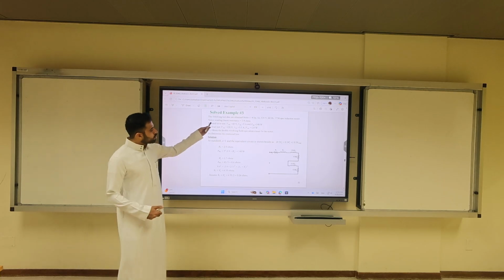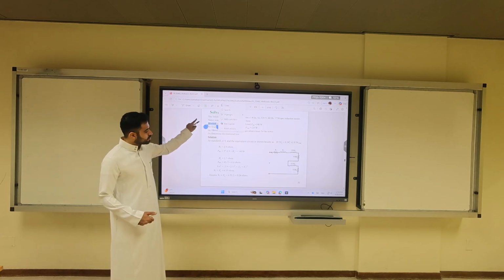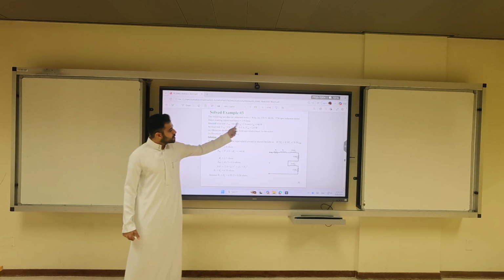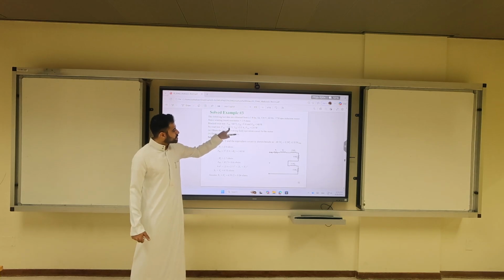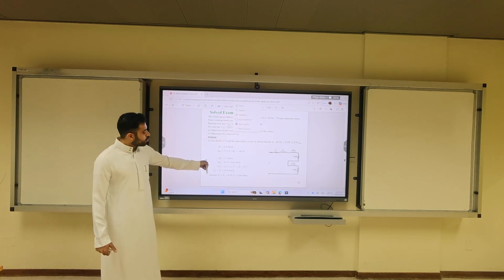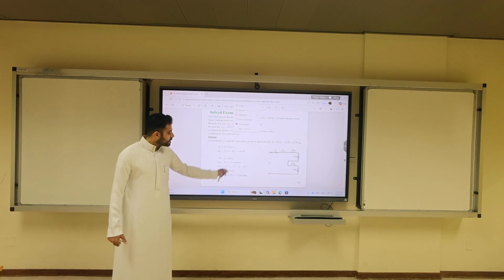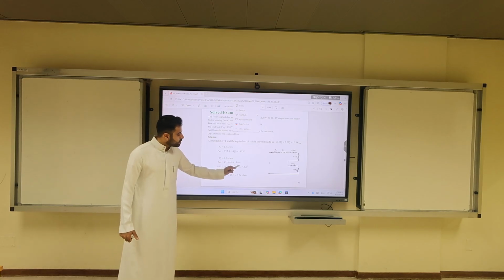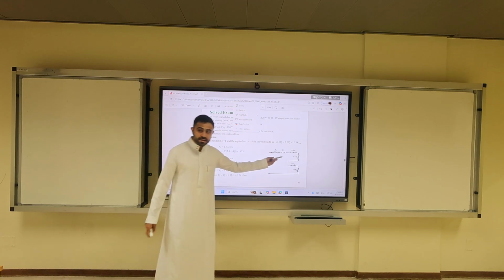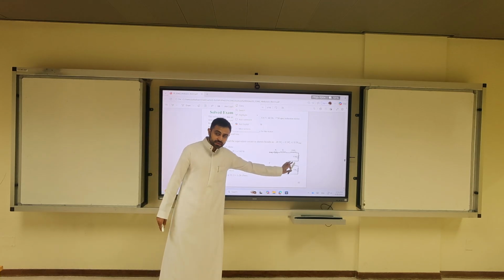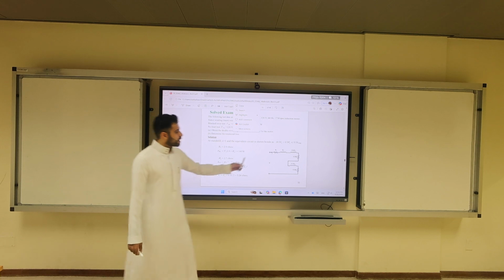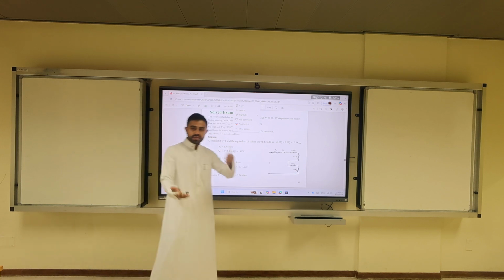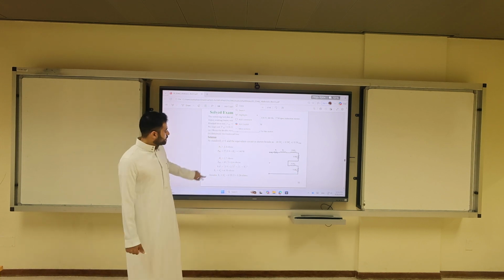From the blocked rotor test, what did we get? We solved using these quantities. This is rated current, this is rated voltage. We solved the equations and we got the equivalent impedance, and then we assumed X1 and X2 prime are equally separated. They are not X-mag, not yet to be found. This is like the stator and the rotor, they have similar windings.